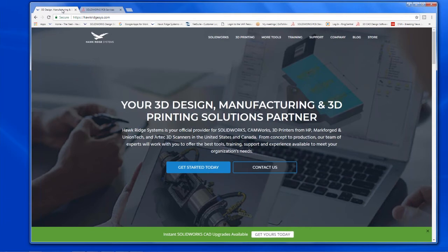The collaboration portion is what is provided with the SOLIDWORKS PCB standalone connector product that is exclusively for Altium Designer. That product license is tied to Altium Designer. The value of that is it allows a single Altium Designer to collaborate with multiple SOLIDWORKS users, because we saw in SOLIDWORKS it already contains the capability to connect to the database and to share data back and forth.